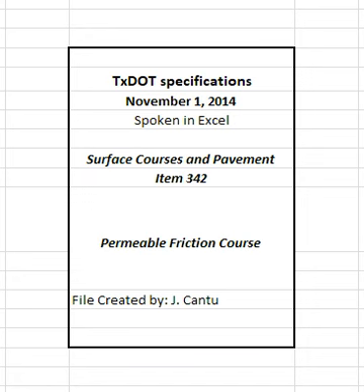May be obtained from asphalt mass flow meter readouts. 4 Binder content is not allowed to be outside the limits shown in Table 4. 5 The engineer may reduce or waive the sampling and testing requirements based on a satisfactory test history.